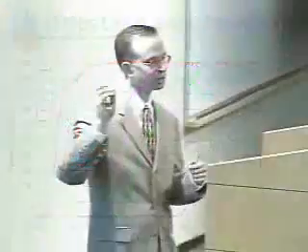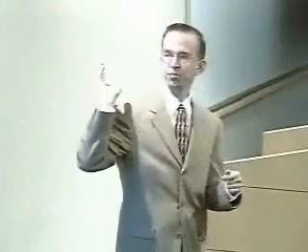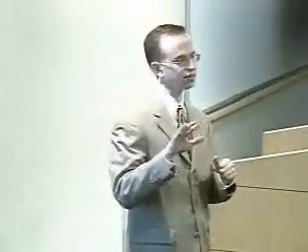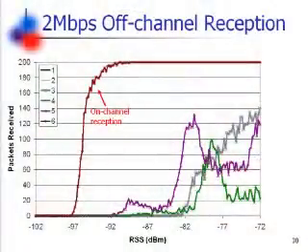The y-axis shows the number of packets that made it through, and the brown bar shows the on-channel reception. That result shows we have a very sensitive receiver, which receives packets down to around negative 100 dBm. Now, as the receiver moves off our channel, we get what these authors expected: a degradation in throughput. So our isolation between these two channels essentially grows, but communication is, in fact, still possible, like these authors expected.